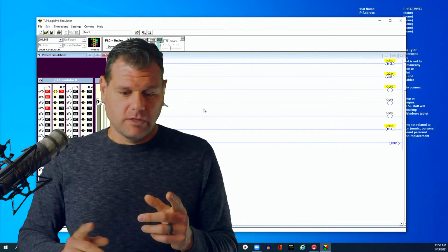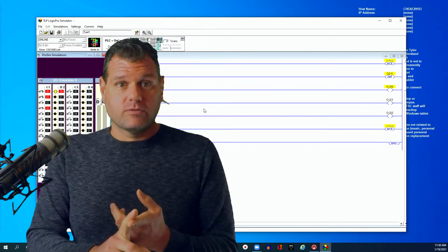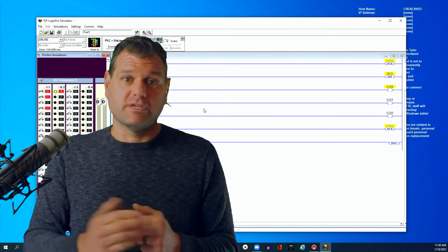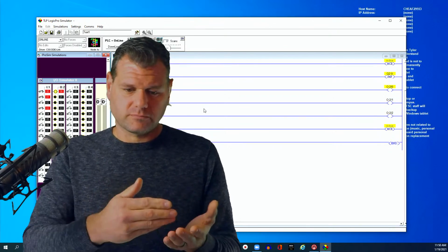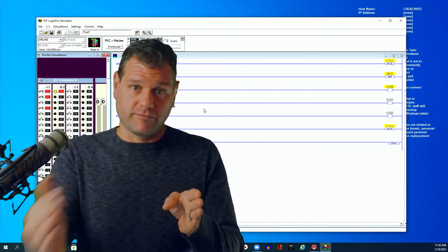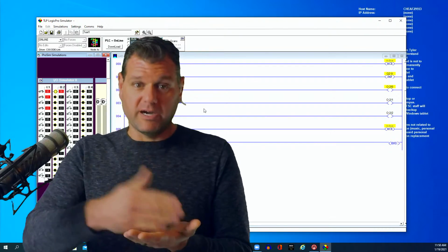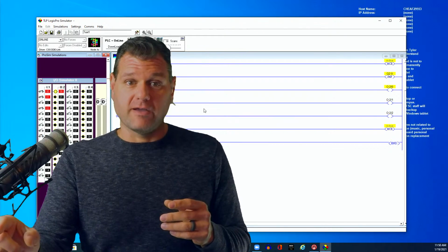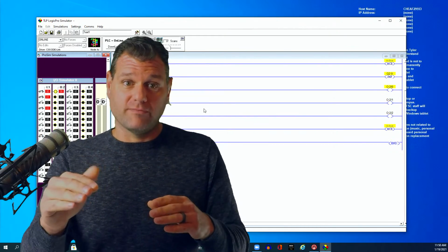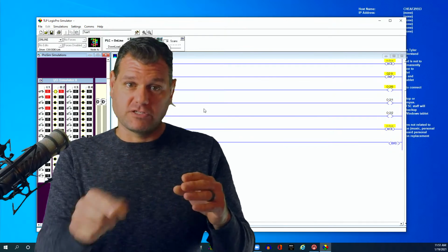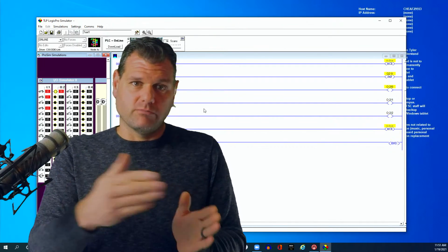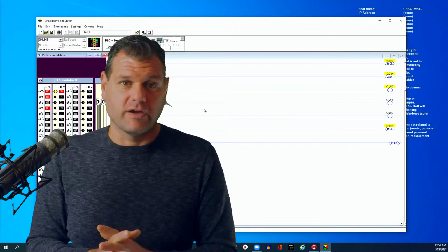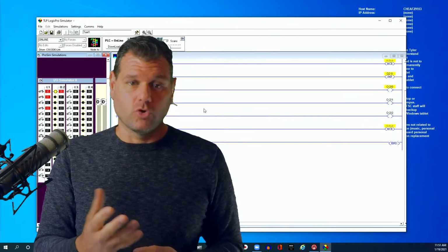Also, a couple things. You can nest, which means you can jump to a subroutine from a subroutine. Just be careful. You can jump so far out that you can leave 3 and go to 4, and 4 to go to 5, and so on. But by nature, when you finish scanning 5, you have to finish 4 where you left off, and then finish scanning 4, and then go back to 3 and finish scanning 3, and so on, right? So it might take too long to go out and all the way back if you keep nesting. You can nest 2 or 3 times, that's fine. Just be very careful.